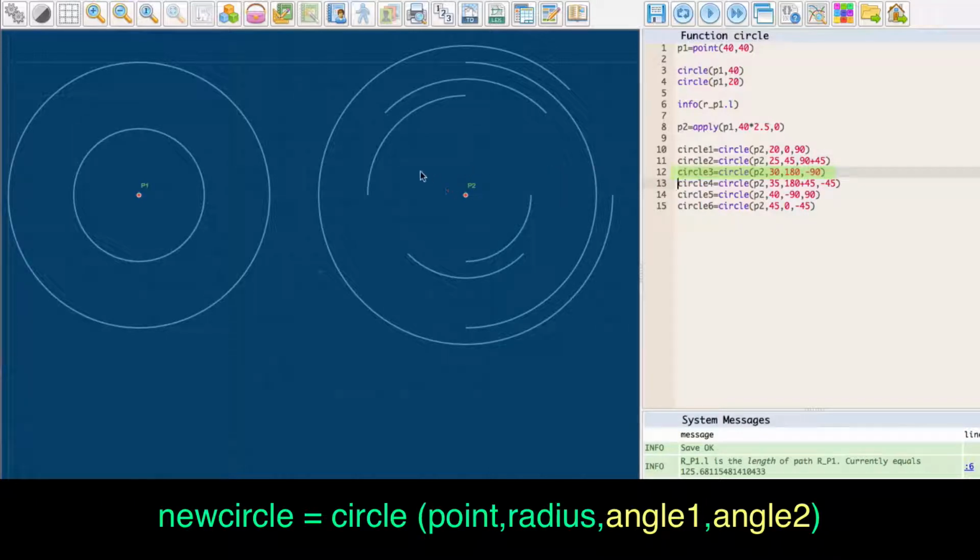You can also use negative values for angles. It will not affect the direction of a segment, it will still go clockwise. Circle 4 goes from 225 degrees to -45, or 315 degrees. Circle 5 goes from -90 to +90, also clockwise, and passes 0 on its way. You may draft whatever segment of a circle, a third, a quarter, a half, or 7/8, as in the case of Circle 6. It will go clockwise for as long as you tell it to.